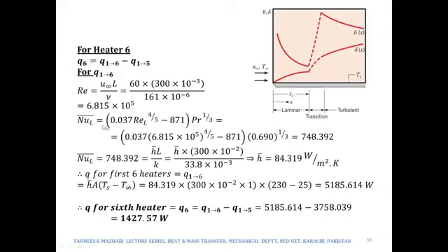So we will be using the mixed flow and not the turbulent flow, because it is not turbulent flow over the entire plate. When we talk about the entire plate means from 1 to 6. It is not turbulent over 1 to 6. Rather from 1 to 6 it is laminar, and then after transition it became turbulent.